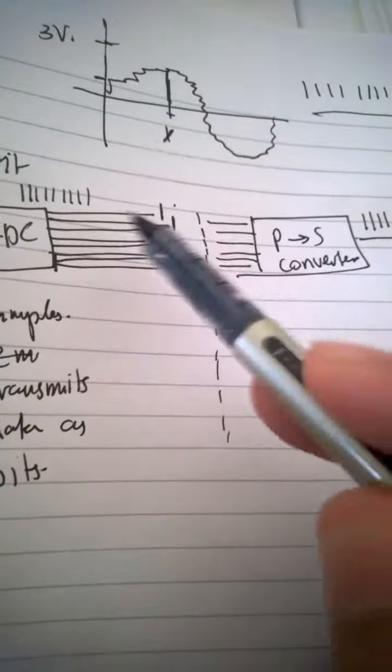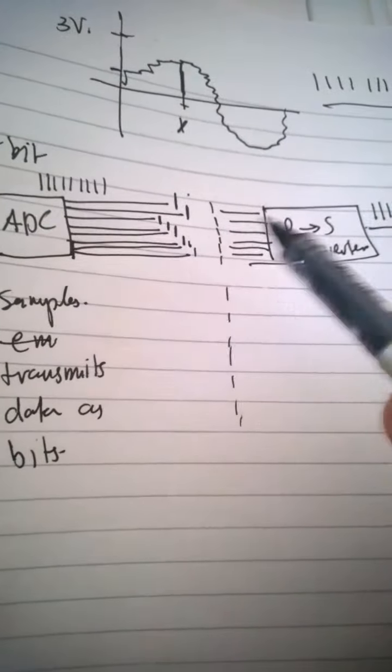So it's receiving data from 8 different channels in parallel, and giving an output of a single channel, but the single channel carries the whole data instead. There are certain advantages to this: in the parallel form we need 8 wires for transmission of data. If we did not have the parallel to serial converter, we would need 8 wires to go to the modulator.